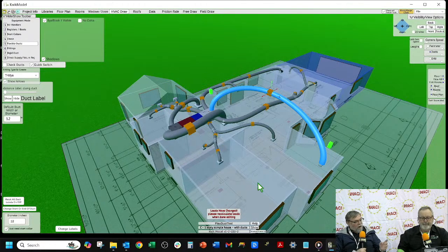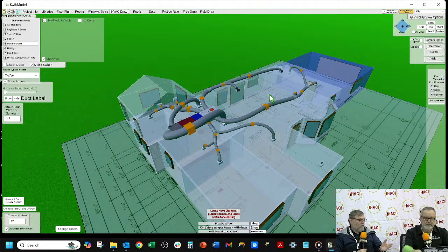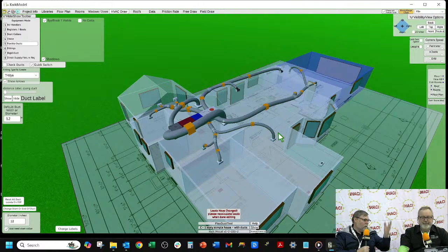Right. So doing what-ifs is a big thing on here. Yes. Let's say I wanted to change the windows. The guy had single pane aluminum windows, and I wanted to go to low-E or maybe even triple pane windows. If this were Minnesota, you might want to do something like that. And if you want to do those kinds of what-ifs, it's a lot easier with the load calc software to just make one global change. Is that easy to do with Quick Calc? It's very easy to do.